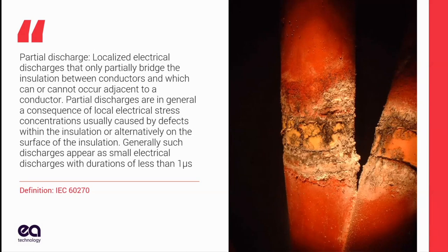Partial discharge, and this is the IEC 60270 definition, is a localized breakdown of the insulation. So if you think of the insulation system from the conductor to ground, a complete discharge would be a flashover, a catastrophic failure. But it is possible for part of the insulation to discharge and actually have a spark and have a current flow, but it doesn't bridge the entire gap. And that's what we're talking about today. This can cause a variety of effects. Some that are useful because we can use them to detect it, some that are harmful that cause failure. And that's the textbook definition of partial discharge.